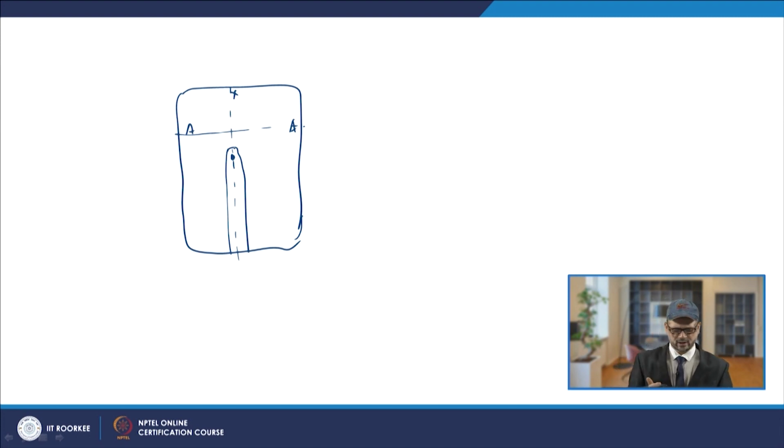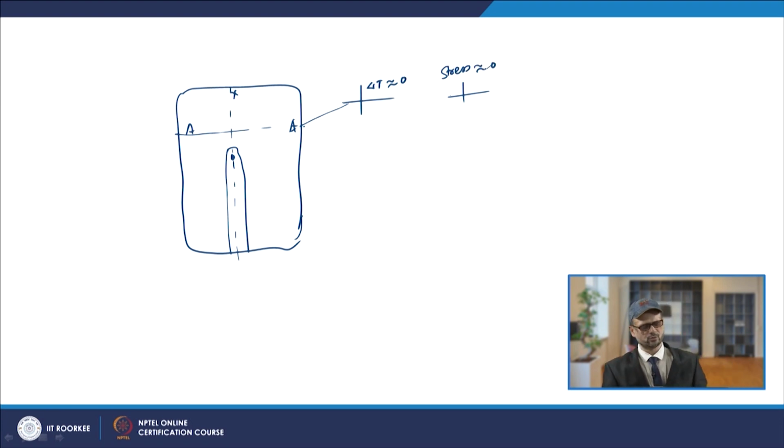In the melted zone, if you talk about the change in temperature and the longitudinal stress value, just ahead of this you have delta T. At this point delta T is 0, so your stress will also be 0. Now, if you look at this section, which is BB.